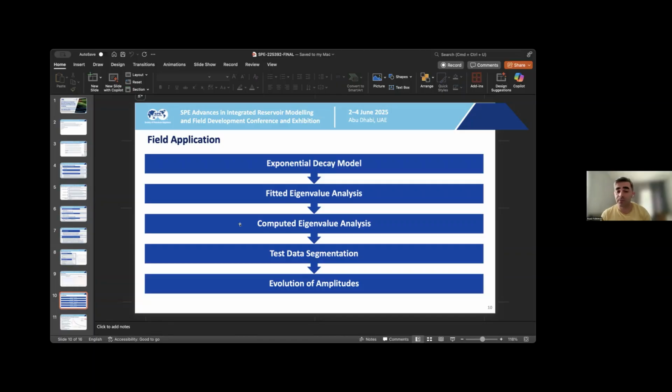So that's why you have to segment the data into 3 or 4 portions, each 60 minutes, and compare those portions and see if you have a convergent case or a divergent case, and then evaluation of amplitudes. Remember what I was talking about, the amplitudes of the oscillations. Those are the amplitudes, the heights. If you follow the real data, those amplitudes should decrease because your temperature should converge to the in-situ value, and then the amplitudes of those oscillations should decrease.